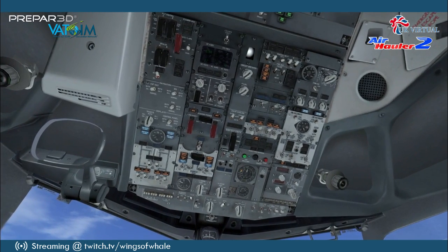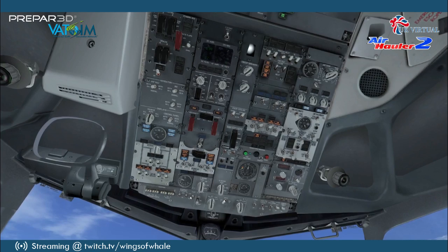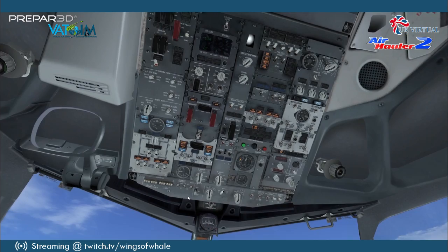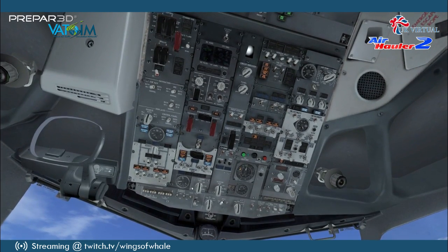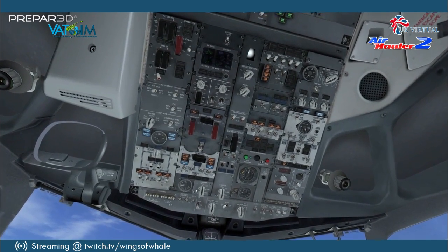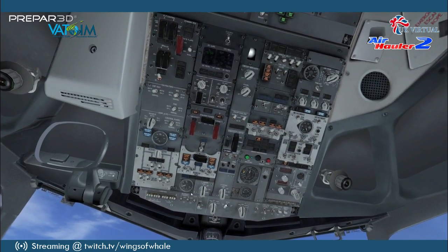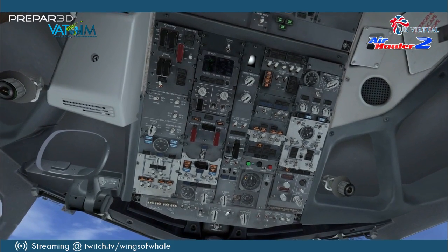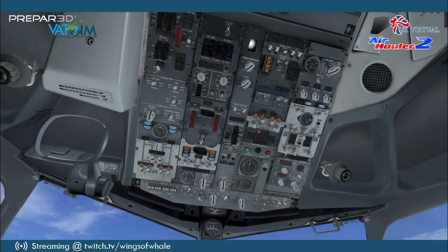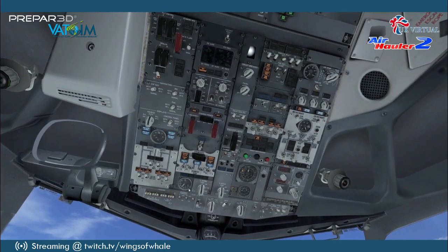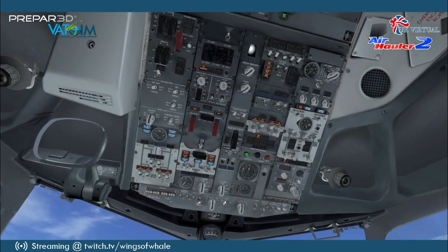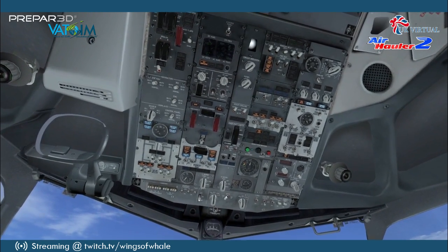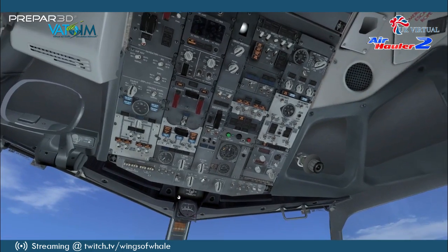And there's a setting in the PMDG options where you set your cold and dark, and you'll see an option in the PMDG aircraft options to set up the long APU option, which is about 3.5 minutes. That's the realistic APU startup time. Or you can set it to the short time, which is about 30 seconds, which is what I've got it set to. Or I believe you can set it to instant as well. It comes on straight away, but I prefer to have a little bit of realism. So I set it to 30 seconds.